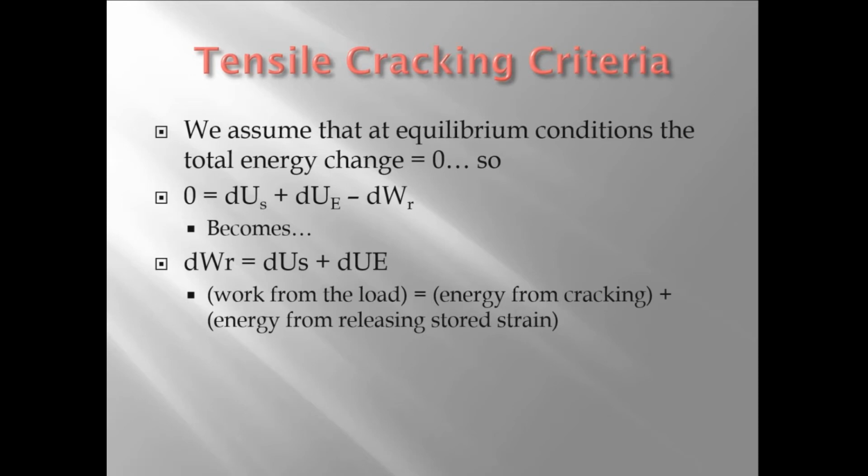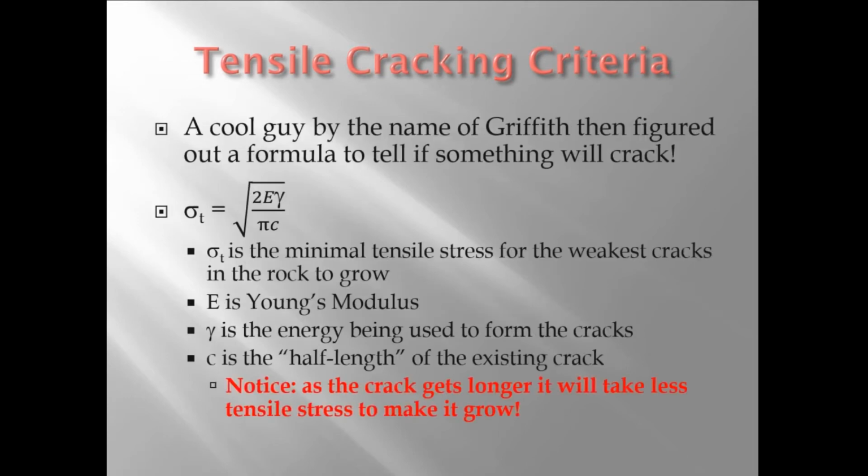So if the cracks don't get big enough, they don't release all of the stress you've applied. That's why shear cracks go all the way through. They relieve all the stress. That is important when we look at the size of the Mohr circles and what happens when the rock breaks.